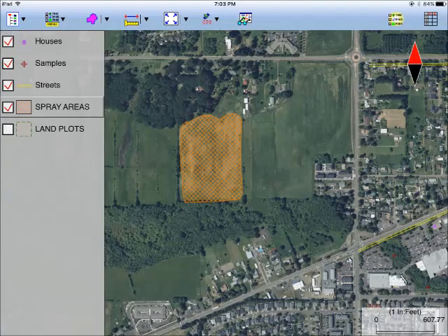ICMT-GIS3 and ICMT-GIS Pro users can use the Insert Node function on the Tools menu to add one or several nodes to a line feature or area feature. The new nodes can then serve as handles to help change the shape of the feature. This functionality is also provided in PCGIS 9 and PCGIS X.